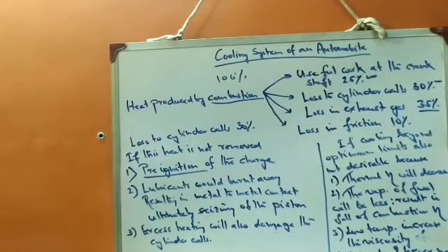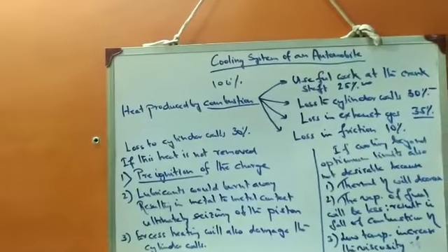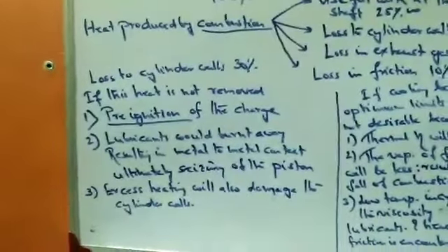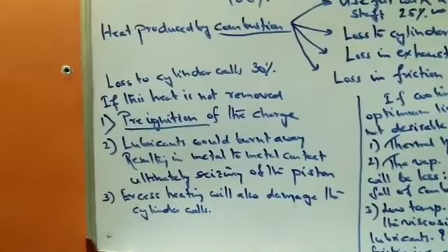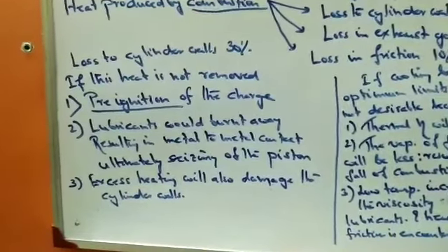If the lubricants are burnt out, direct metal to metal contact will take place, which will cause a further rise in the temperature of the piston, and ultimately the piston will seize and melt with the cylinder walls. This is a very dangerous case, and the whole engine block will have to be replaced.